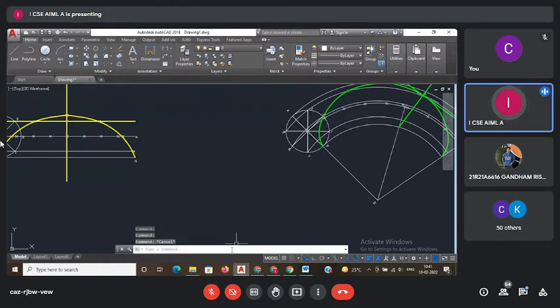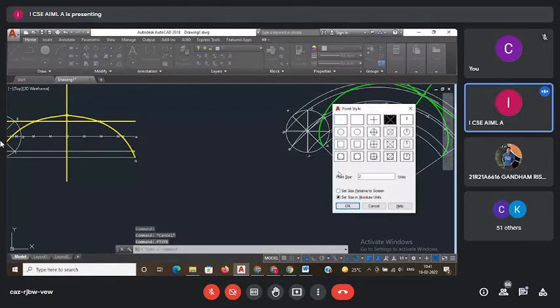Okay, that is the PD mode. Type PD mode, M-O-D-E. PD mode. Suppose you forget this command and you are not getting the points. If you forget this command, you have to remember only one command. That is point type, PT. That's it. PT, Enter. You will get any one point.